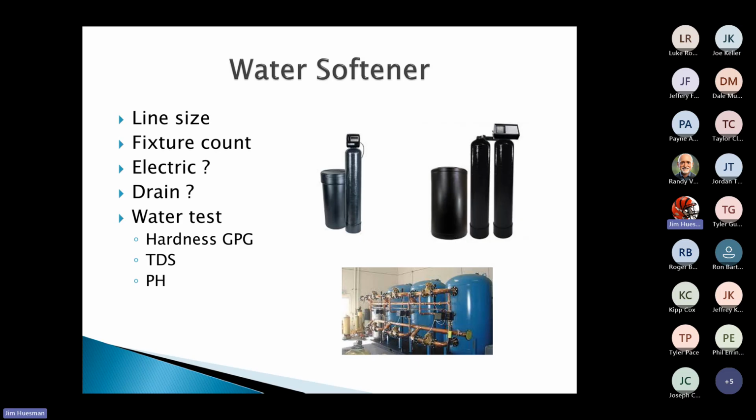The reason is we'll talk about a 1-tank or a 2-tank system in a minute. Fixture count is extremely important. I'll add in the type of building, because if we're softening water for, say, my house versus a hospital, at my house there's some downtime. A hospital has no downtime. We'll explain why.